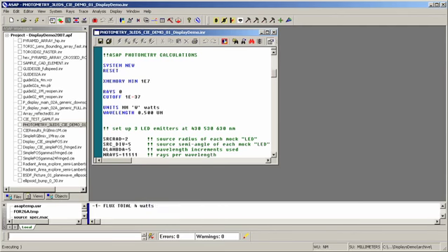I'm going to run this with a fairly small number of rays first. Basically, I'm running 81 wavelengths per LED and 11,000 rays per wavelength. So that is a modest number of rays for a colorimetric analysis. I'll show you that result, and then we'll get the result for a great number of rays so that you can see how color noise improves as you use an appropriate number of rays in the analysis.